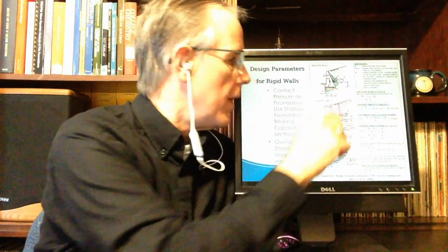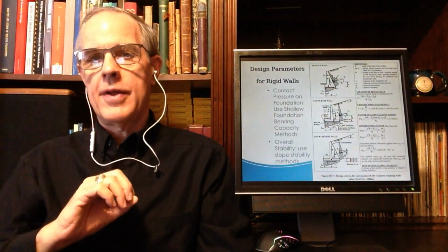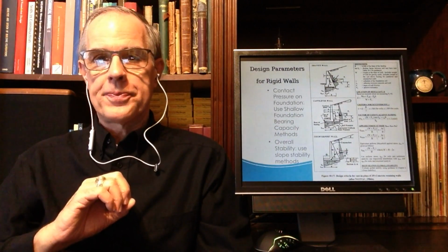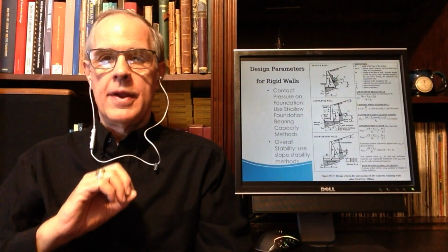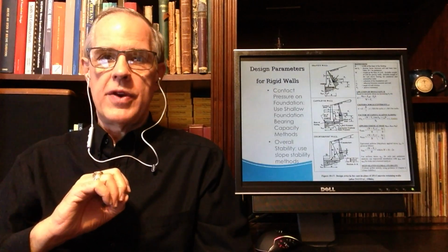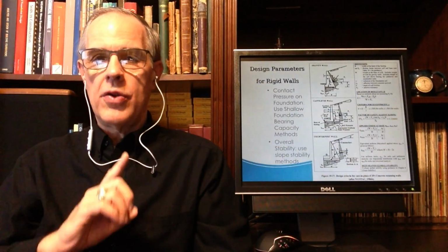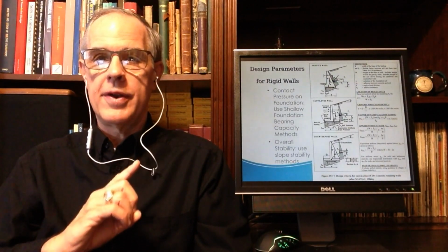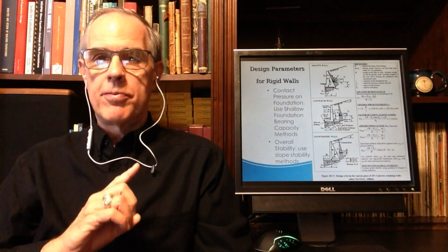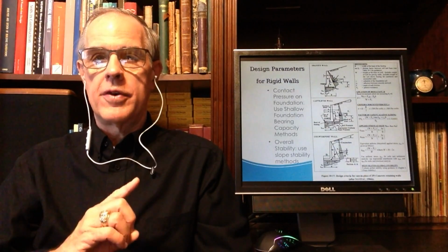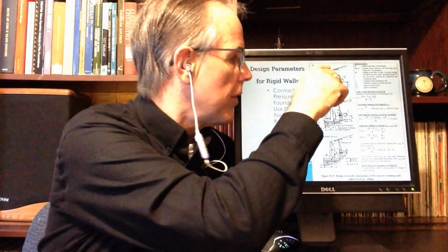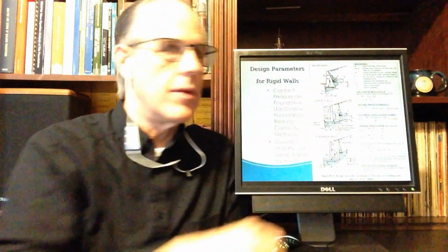And actually it's two ways. We talked about this with bearing capacity, and inclined loads, and I told you that the way we deal with these with retaining walls, and probably the best way to deal with them, period, is to break them up into horizontal and vertical components. The vertical component is straight down.